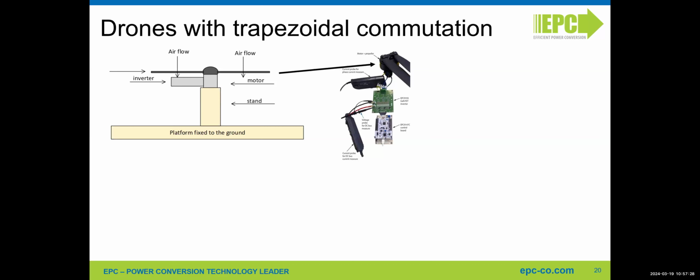So the main point is really thermal. Look at what your worst condition is from a thermal point of view, and check if your system is able to do it. So from that point of view, rotor lock or operating condition, a low frequency is not really making the difference.